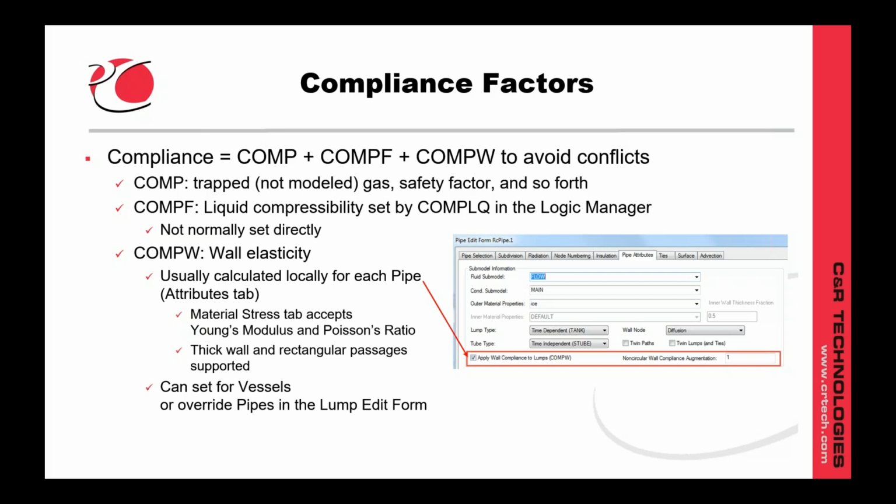Compliances can also be set for vessels or compartments, and you can override pipe level compliance using the lump edit form.